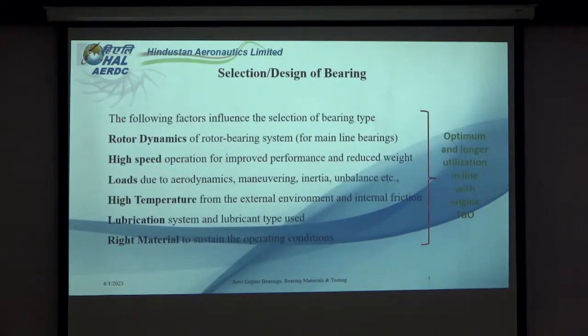Therefore, for the selection and design of bearings, these are the factors which influence: rotor dynamics of the rotor bearing system, high speed operation for improved performance as well as reduced weight, various loads such as aerodynamic, maneuvering, inertia, and unbalance, high temperature from the external environment as well as internal friction, the lubrication system and lubricant type used, and the right material to be used for optimum and longer utilization in line with the engine TBO.